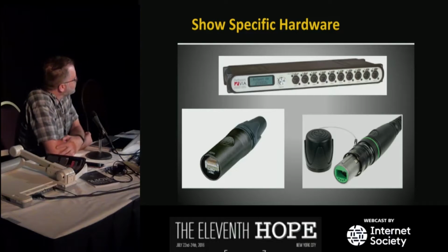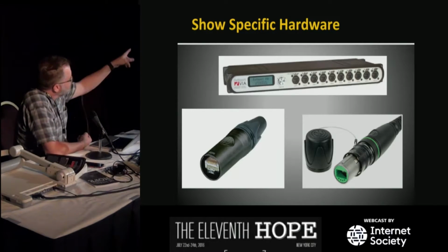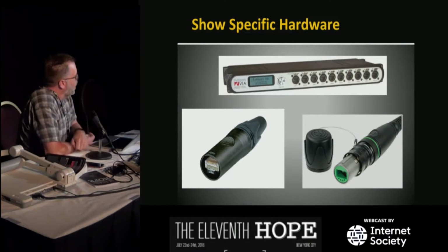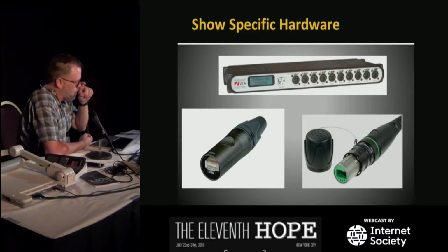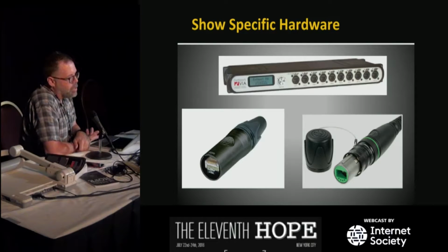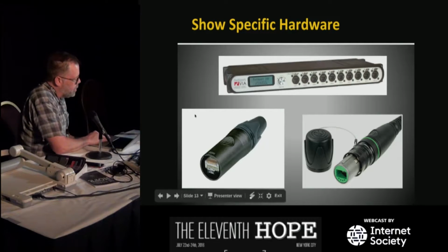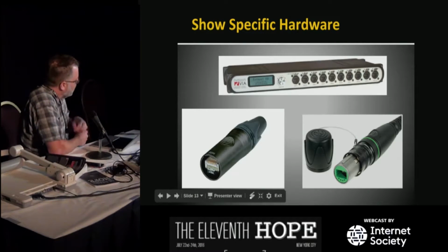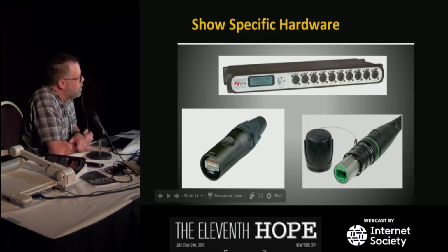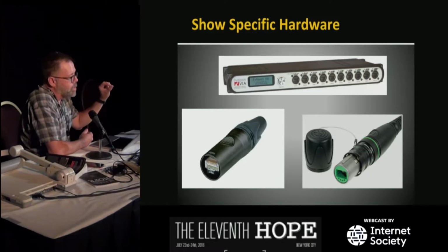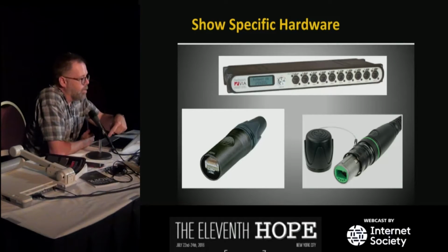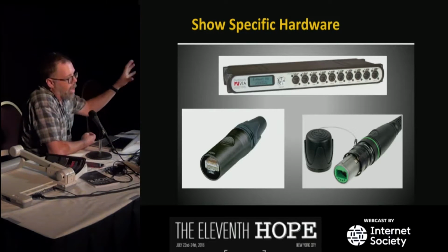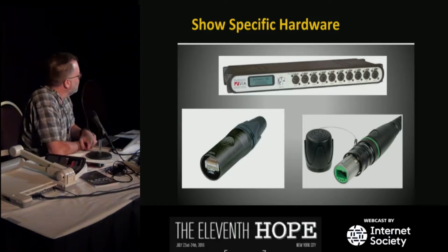That said, we do have some show-specific hardware. The switch on top is made by a company up in Canada called Pathway, but they got bought by somebody, so the name is very complicated. That's basically a standard switch, but it knows about the protocols we use. It has these kind of connectors on it. If you can see that, that's called an EtherCon connector, a standard RJ45 connector that fits inside a shell that's the same size as an XLR connector, which is what comes out of this microphone. So we already know we have panels punched this size, all this kind of stuff is there.